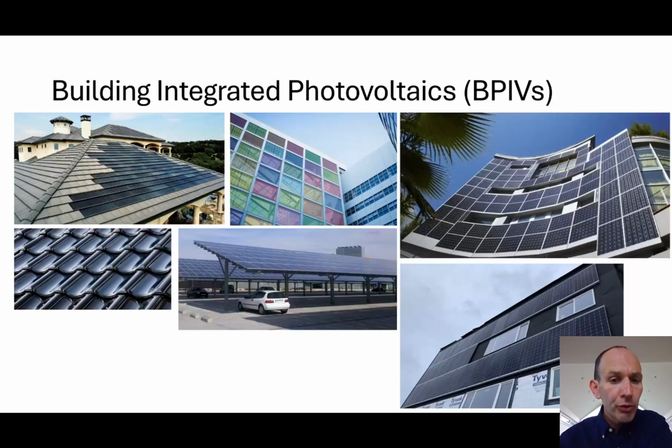They can be on a roof, or they can be on a wall, or they can be really anywhere that you think is feasible. The two important things for solar PV are that it faces generally a southern direction, though they can be east or west to capture morning or evening light. Also, they need to be fairly unobstructed from surrounding features. There are other impediments in terms of grid connection or electricity connection, but generally speaking, that wouldn't be something that we would worry about just so much. So building integrated PV is really important.